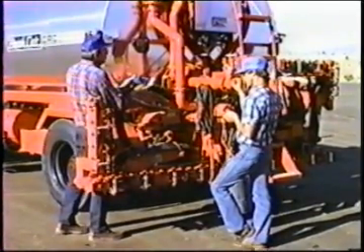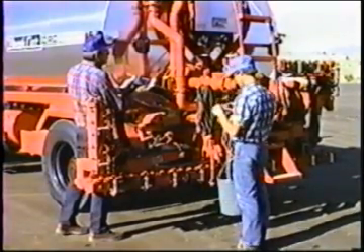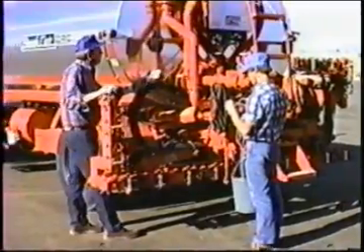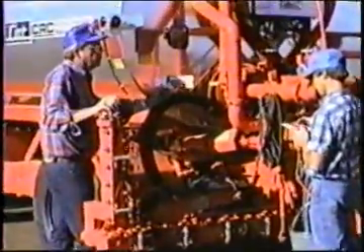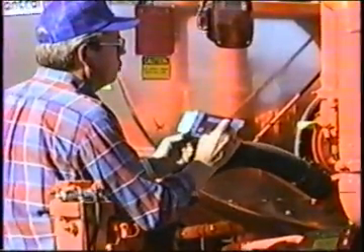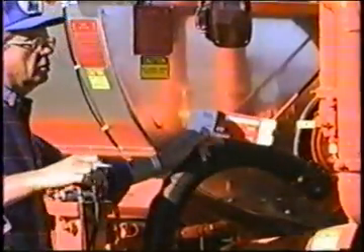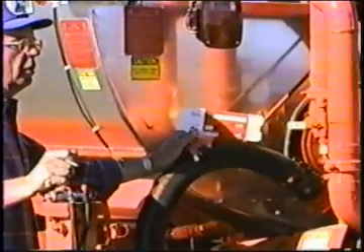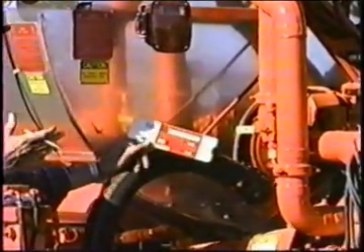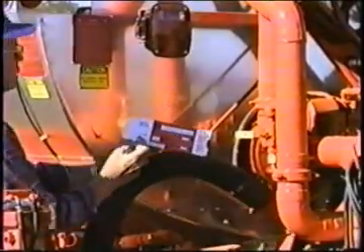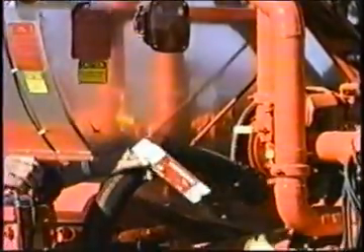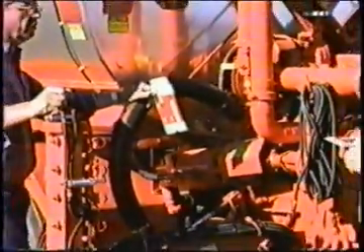If you speed up, 0.25, move it over to 500 feet per minute. Okay, the number 3 nozzle right then went up to 13 pounds of pressure. Because now on 12 feet of bar, we're pumping almost 170 gallons a minute through that same nozzle size. Pushing more material through it makes higher pressure, and we see that the pressure went up to 13 pounds. 13 pounds is going to start to make some overspray.